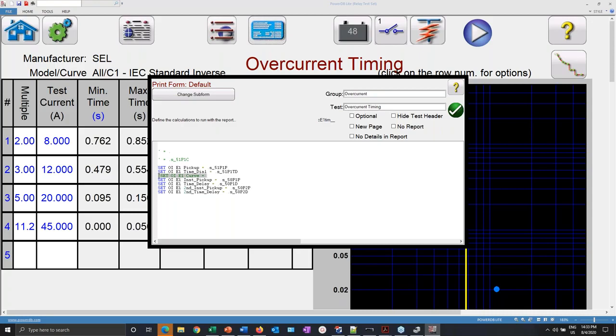I have left the curve for later because the curve has a different form coming from the relay than the form that I have for the curve on the software. So we will have to do some matching there. Fortunately for you, we already have the scripts to do that kind of matching.